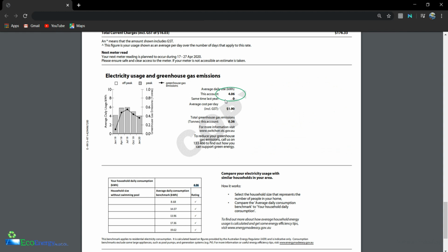There is a loss factor for PV systems of 1.3 that we have to incorporate in our calculation. So 1312.9 will include the losses in the system.